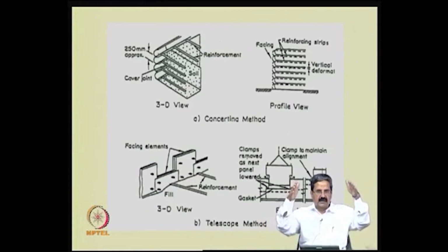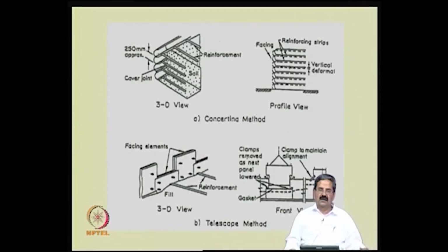So, you can do that instead of a conventional 2:1 slope, where 2 is horizontal and 1 is vertical, like which you do, right. In an embankment problem, we need a 2:1 slope, which a slope factor of safety cannot give you, steeper slopes. But here with geotextile you can achieve that steeper slope. The difference is the material and the way it is done, geotextile.